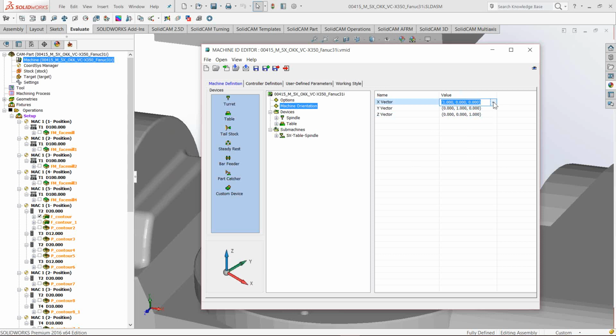And if you have the mill turn, you just write the X. It's actually my Z. My Z is actually the X, and the Y-axis is flipped, correct? Some of you who are familiar with the mill turn will know what I'm talking about. So my X is actually the Z. My Y, I said, is flipped, and my Z is actually X.